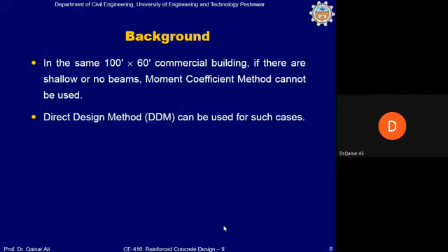If they are used in zone 2A or 2B instead of slab without beams, then by and large, the slab with beam system will be economical as compared to slab without beams. Although the overall cost may not vary too much, because of saving of one story in the structure and saving of accompanying masonry and all other associated material involved in every story, ultimately it will depend on the situation which system is economical. From the structural point of view, from the reinforcement and the concrete material, the slab with beam system is generally the most economical system.